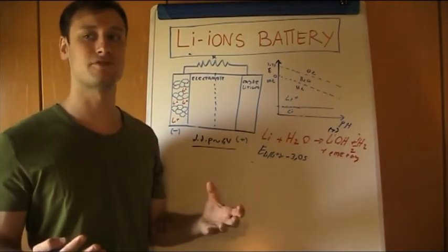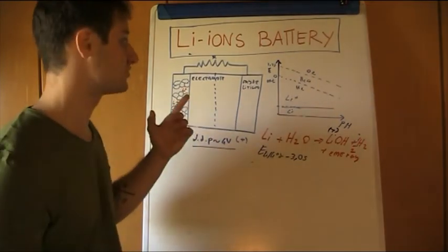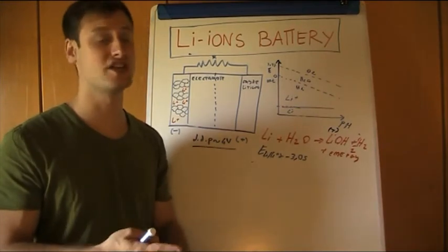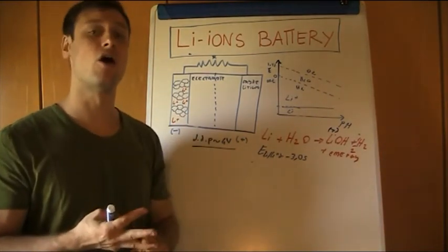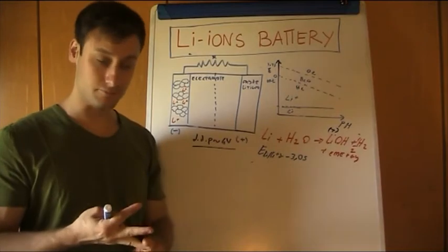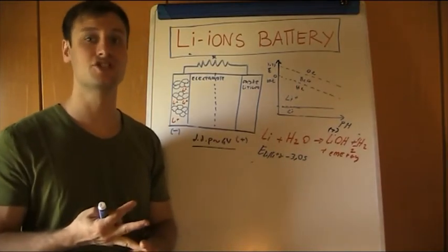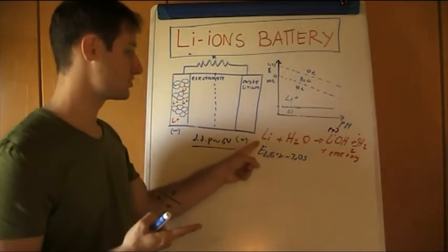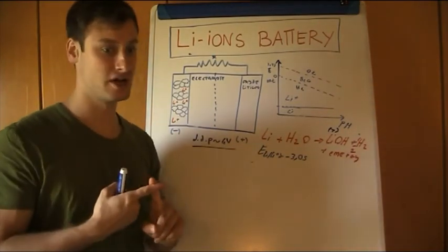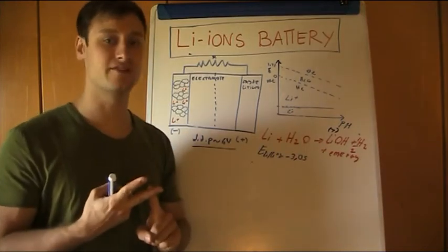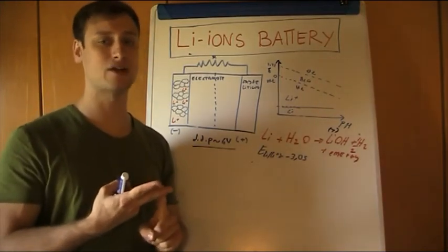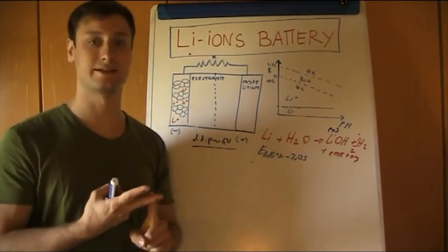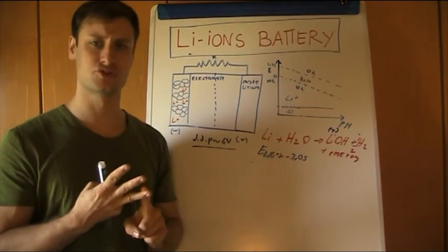So these are the different problems concerning lithium-ion batteries. Even if we have a huge output voltage, a high energetic efficiency, an extremely high number of cycles for charging and discharging, and use stability, the main problems are the hazards connected with lithium's interaction with water, the possibility of generating a short circuit if the recharging process is conducted in a bad way, pushed too much or too quickly, and bad stability at high temperature.